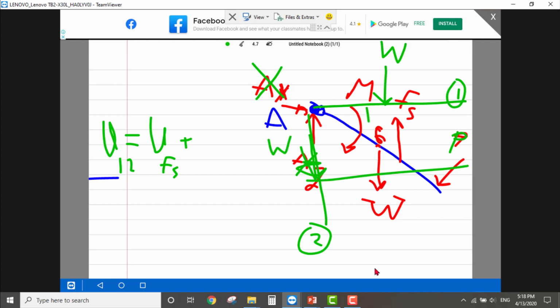There is a certain displacement in the y-axis between the first and the final state. And this displacement is in the same direction as the weight, so we have work due to weight. How about the moment? The moment is the same, because we have theta equal to 0 and then theta equal to 90, so yes, we have work due to the moment.